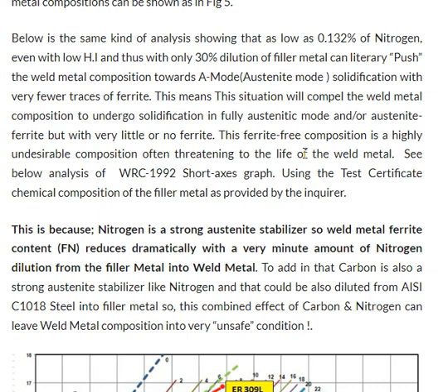Why is this small ferrite content so important to the weld metal? Because the presence of ferrite in a weld metal can absorb the low melting point elements like sulfur and phosphorus that may be accidentally present. So ferrite is a sink for those low melting point elements, which otherwise can wet the grain boundary and segregate, because they are the last freezing elements.